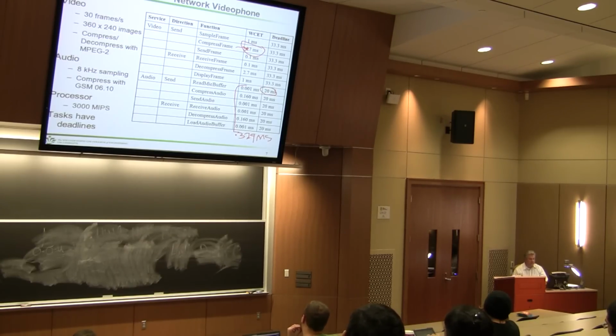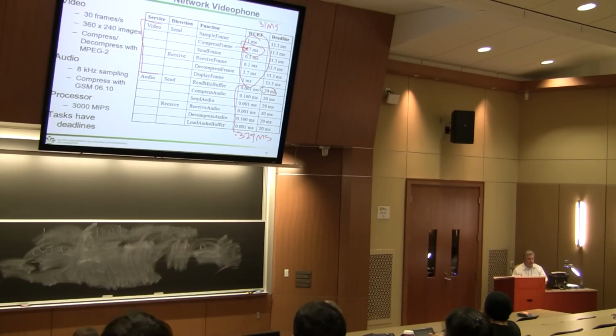So 3 to 4 milliseconds is definitely enough time if we had everything going up here. How much does all this time up here take? Let's see, 27, 28, 29, 30, 31. So that looks to be about 31 milliseconds up here. So if, in the process of all of this video stuff running, we stop for a moment and handle this, which takes less than 1 millisecond, right? And then it goes back and executes this. Will we ever miss a video deadline?